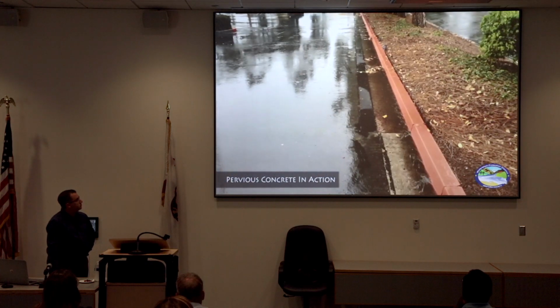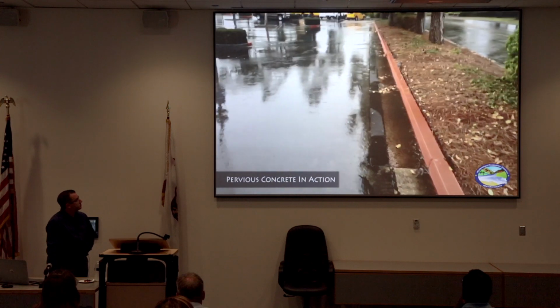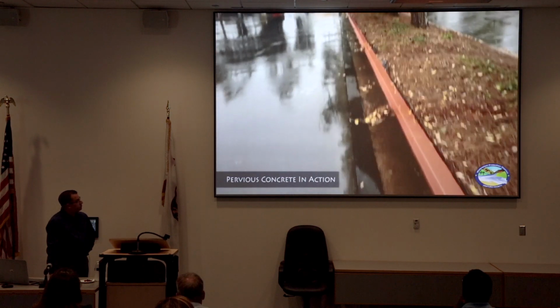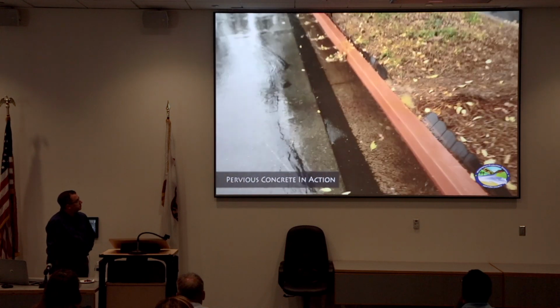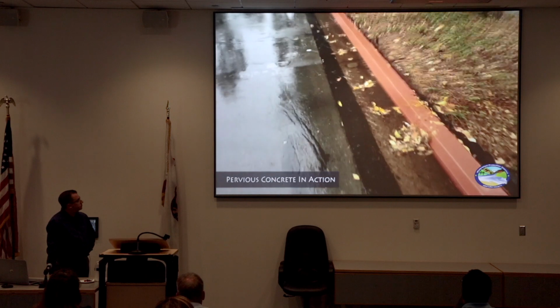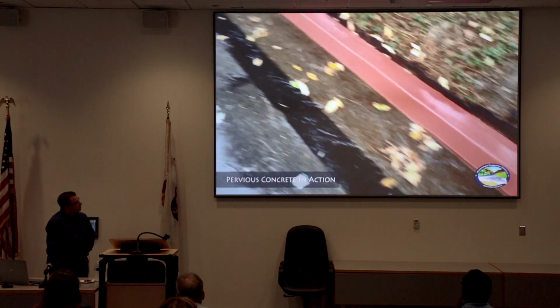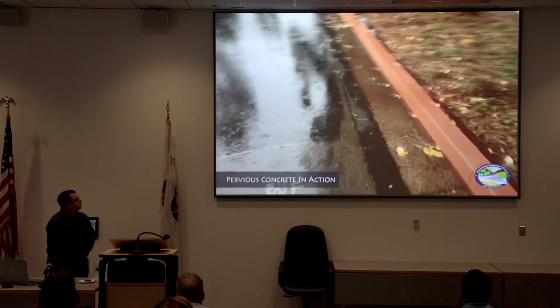So here's lot G. It's about 1:40 in the afternoon on December 2nd. So we've had probably a good 5.5 to 6 hours of rain at this point, fairly steadily. So you see here the gutters are kind of filled up. Overall, the system is inundated. Here's one of our observation wells that's underwater. So there is infiltration occurring here on the gutter. It says there's too much water.